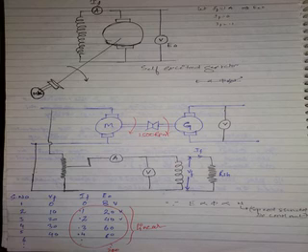Ohm's law. You can expect, you are applying DC, expect the same thing. You are applying DC voltage. So you think of the circuit like this. There is some resistance here. What is this resistance? Original field winding resistance, 50 or 100 or 250 ohms, like that. So the original field winding resistance is there.